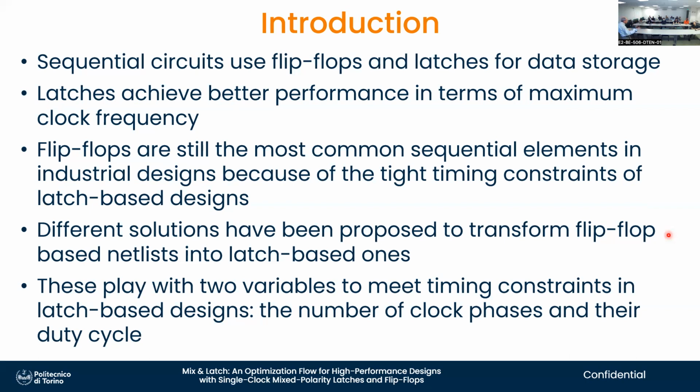If you're a little bit slow, you can walk through it while it is open, and if you don't have too much work to do on the other side, you can still make it to the third door in time. So latches are more complex to use, but provide better performance. And we have been trying to work with the strength of the flip-flop based methodology and the flexibility of latch-based in this work.